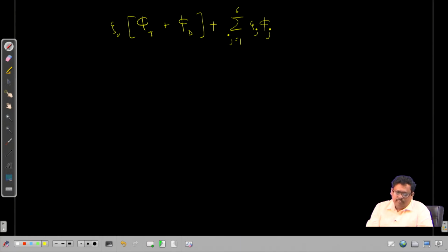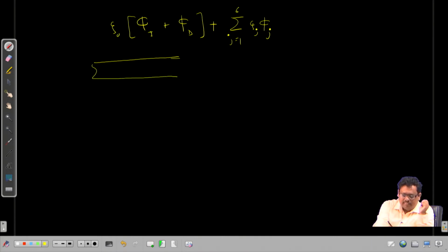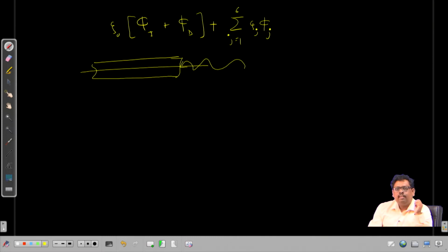Now, if you look at this physical phenomenon, what is happening? I have a ship over here and then this incident wave potential is actually hitting this object. Because this wave hits this ship, we have some pressure variation along the hull, right. If you integrate the pressure, you can get a force of course, and the name of the force is the exciting force.